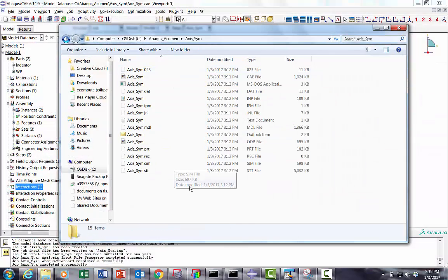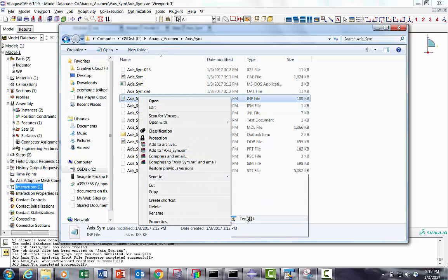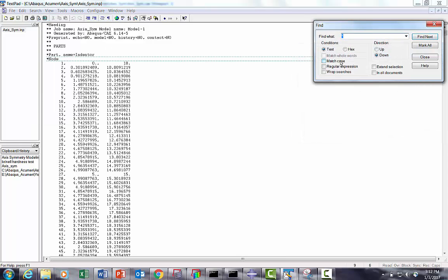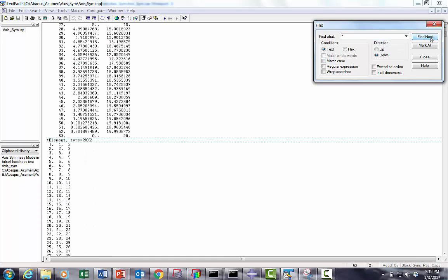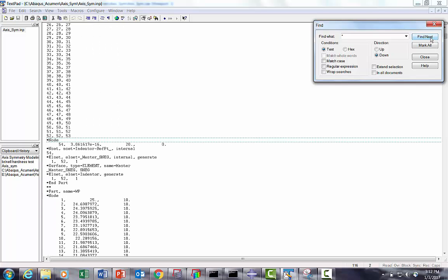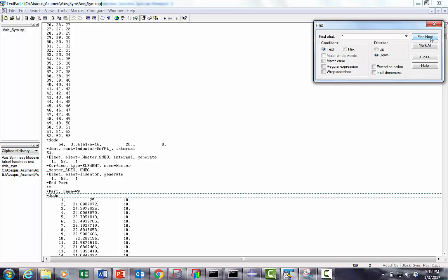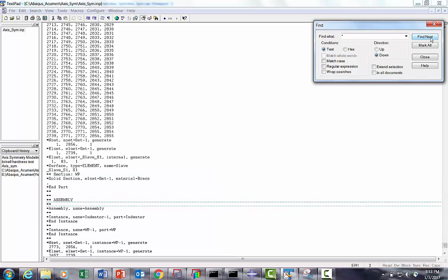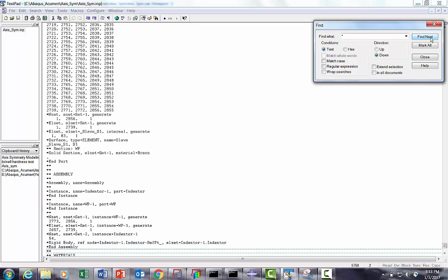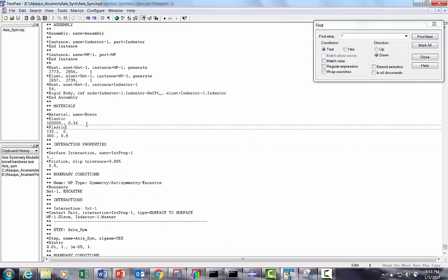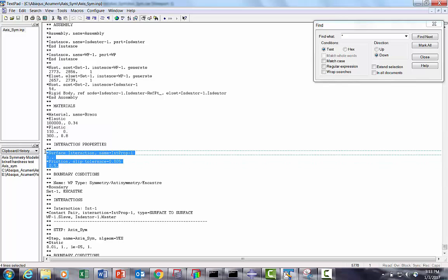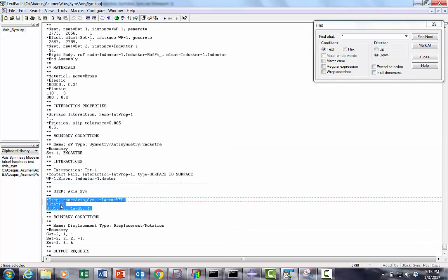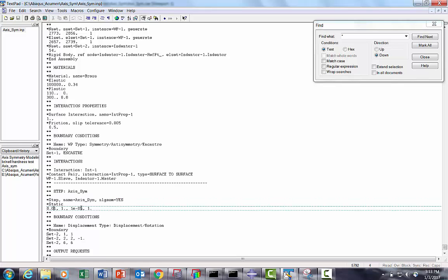Let's look into the input file, how it looks. I generally use TextPad, and I also recommend TextPad is better. Notepad is also fine. So we have the nodes, then this RAX2, it's a rigid element. Then you have set definitions, and then nodes for the part. CAX4 is the workpiece. Then you have the assembly, surface generation, some node sets, rigid body, material definition. You have the interaction property, friction details are there. You define the contact. We give the step details, static, nlgeom equal to yes. We are going with 1% loading to start with.